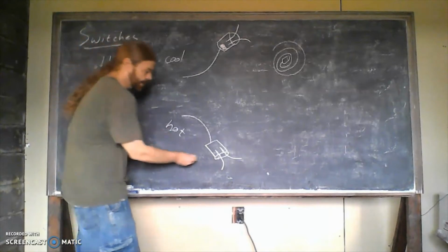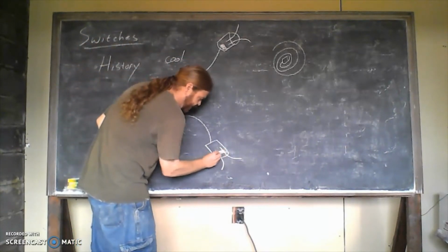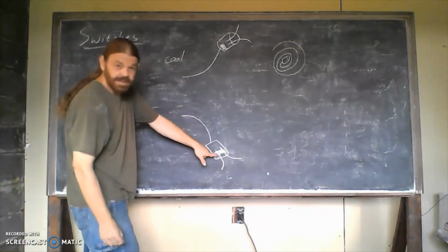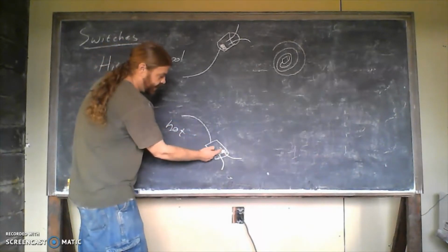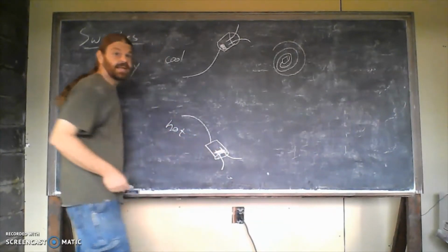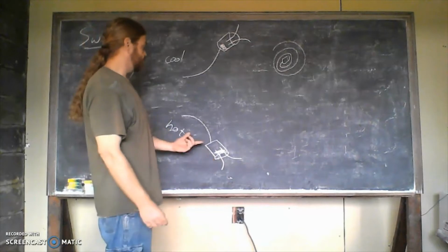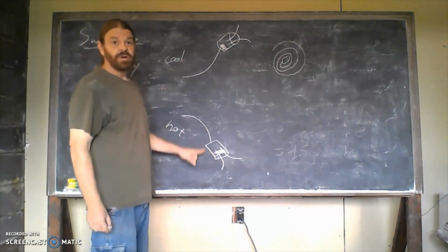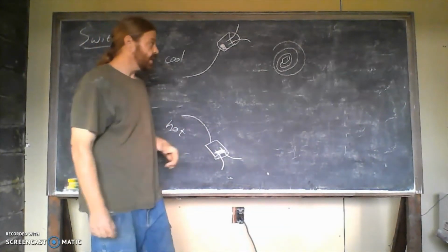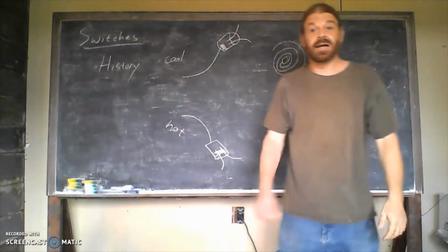But if we heat it up, it's going to curve down, the liquid runs to the bottom, and it's a liquid metal, so it forms a connection there and closes the switch. So we're turning it on and off based off the temperature.